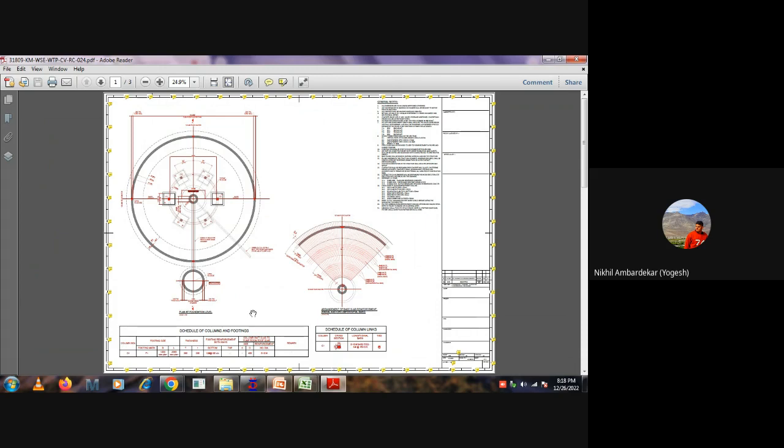these parameters, like what is the height of the tank, what is the internal dimension of the tank, because their calculation is based on the volume of the water. So we have to keep those internal dimensions intact. If they want 5 meter by 5 meter, we don't need to reduce or increase that size. If they want a height of 4 meter, no. So whatever you have to play with, you should play with your thicknesses, base slab, top slab.